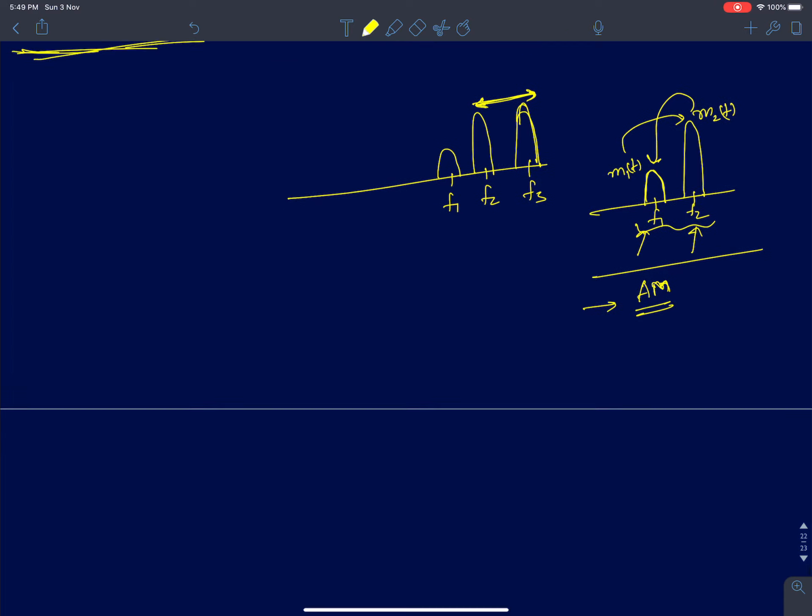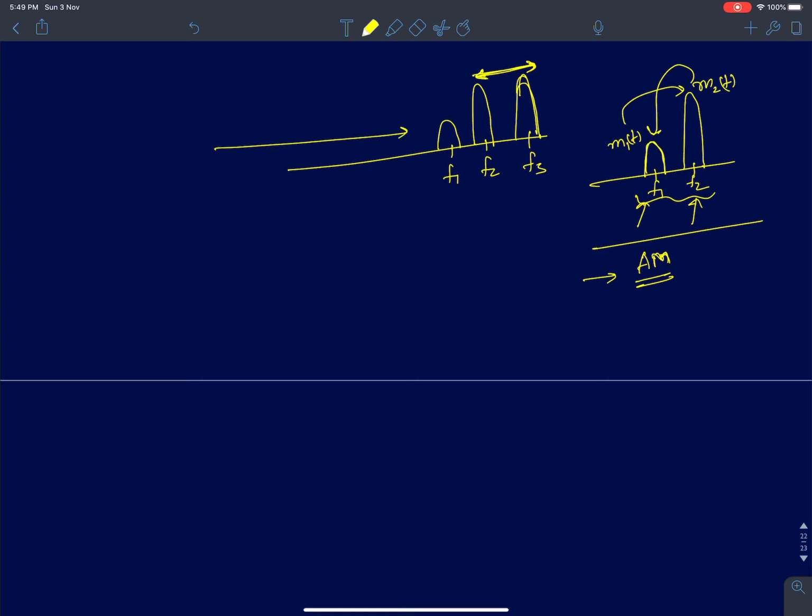Okay, yeah. So now I'm back to this problem of nonlinearity. Now we are discussing cases with two interferers, and this is very common in RF systems. So for example, I'll take the example Razavi's textbook gives, an example of a Bluetooth system. So for Bluetooth, the channel spacing is around a few megahertz. That's the channel spacing for Bluetooth. And you would have 2.41 gigahertz, 2.42 gigahertz and 2.4 gigahertz. So these are the different frequencies that I can have.